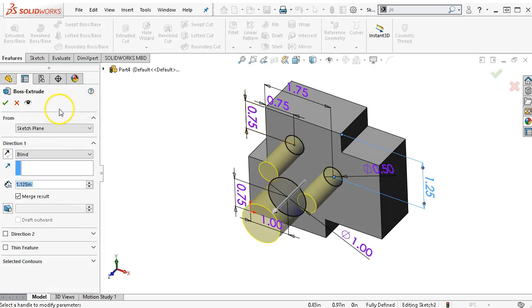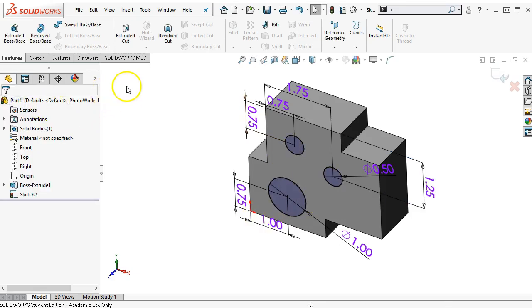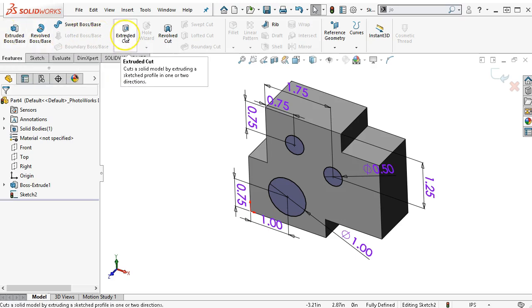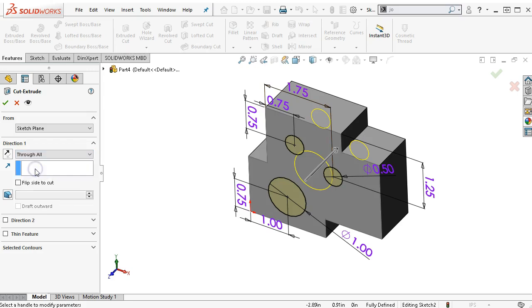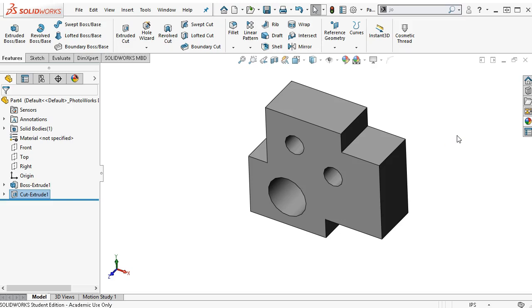and realize that I did not want to make a boss, so we're going to close. That just puts us right back into the sketch, and then we're going to come over to about the second little area here and pick Extruded Cut. And then I don't want to be tied, since these are not blind holes, meaning that they stop before it breaks through the material. We're going to take a look at the end conditions. So the end conditions would be our best choices here, through all and up to next, but we can use just about any of these to complete the geometry. So for now, just to illustrate and get us started, we're going to do through all. And if this was to change from 1 inch 125 to 10 inches 125, these holes would still find their way through the part. So we go ahead and accept, and that gives me my geometry.